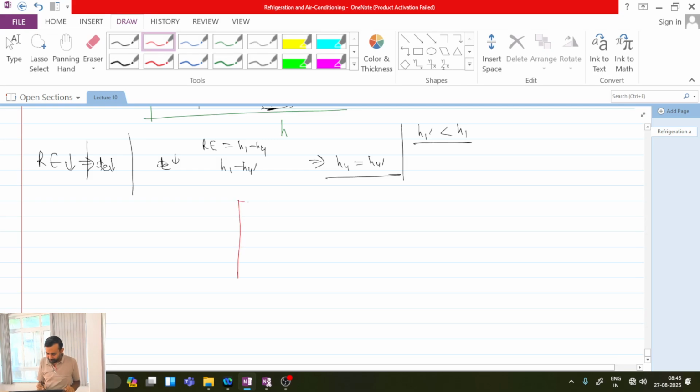Say this is your reciprocating compressor. So what typically has a reciprocating compressor? A suction line and a discharge valve, and then you have a piston. Whenever this piston is moving in downward direction, then your suction port is open and fluid is actually entering inside this. And whenever it is moving in the upward direction, then discharge port is open and fluid is going out of this.